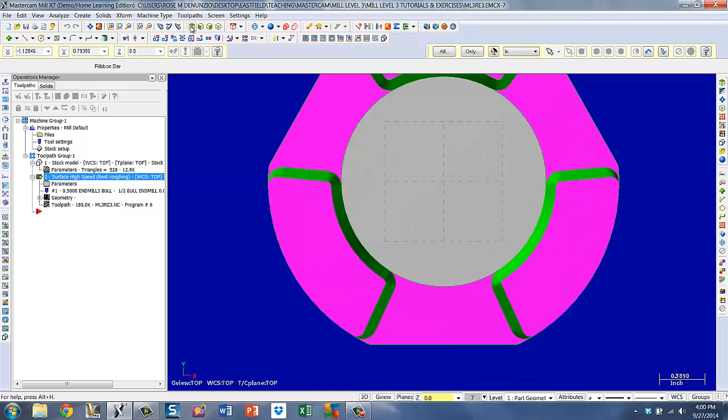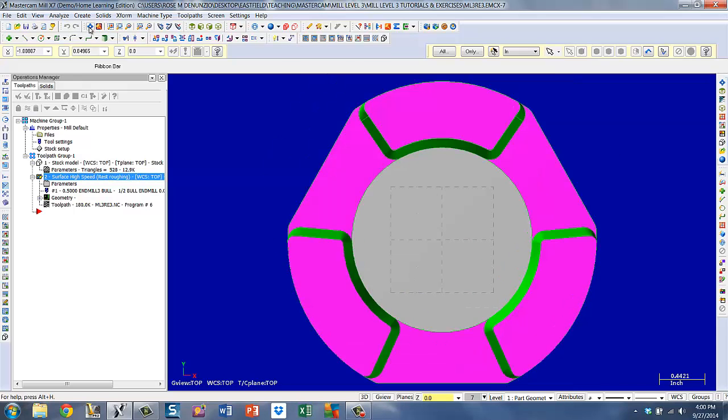I'm going to switch to top view, fit, and it says to use parallel lines, so create line parallel. I've lit up this one just by hovering. It says here select a line, so I select a line. My distance per the text is 0.15. I'll hit enter there. Now it's saying indicate an offset direction, which will be over here. I want to apply it, and I want to put another one adjacent to it right here.